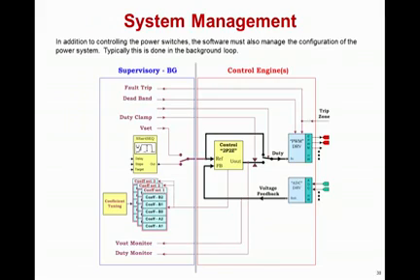There are also additional ways you can configure your software to make it more useful in your end system. This is one example that shows possibly using various coefficients shown in the blue box in the bottom left, having a startup sequence as shown in the yellow box in the left-hand side, and being able to switch in and out the control law at some point to control an output power stage.